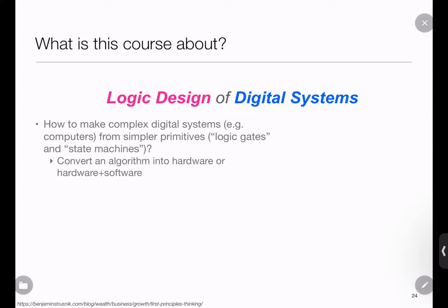The simplest primitive, of course, is a transistor, but a transistor is kind of an analog beast. In itself it doesn't have any digital behavior, although it can act as a switch. Conceptually, you can think of a transistor as having 3 terminals. If I give one terminal a high voltage, it connects the other 2 terminals so current can flow. If I give it a low voltage, those 2 terminals are disconnected. So it's literally like a wall switch, except instead of you switching, someone is sending it a 0 or a 1 to switch. It's a programmable switch.